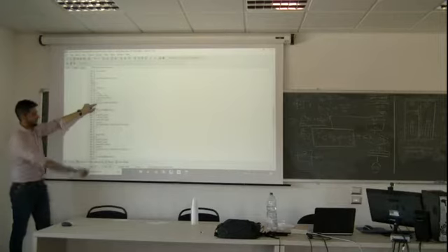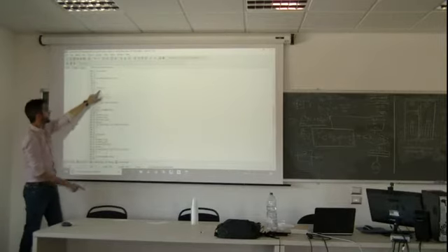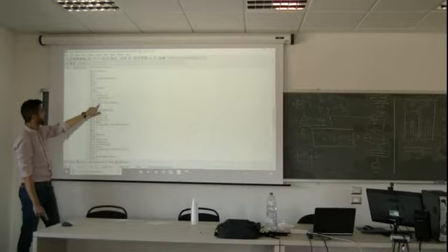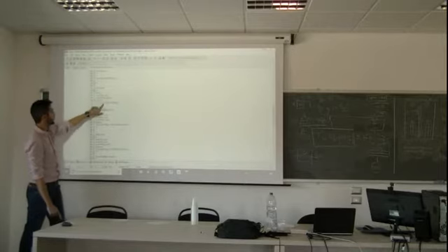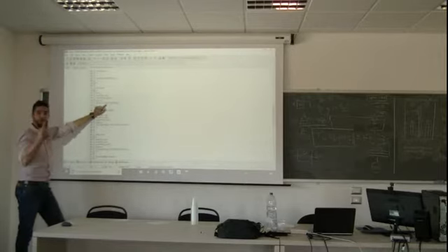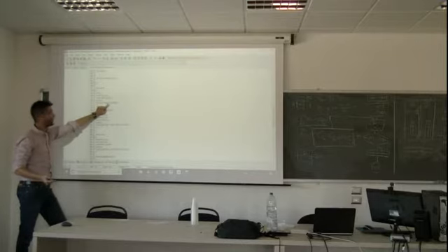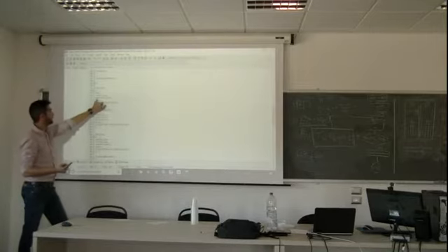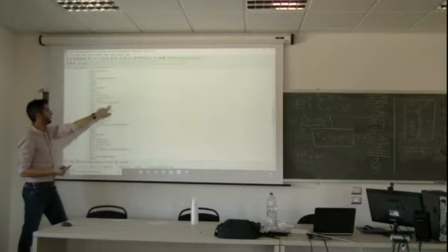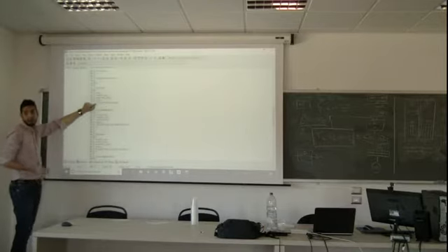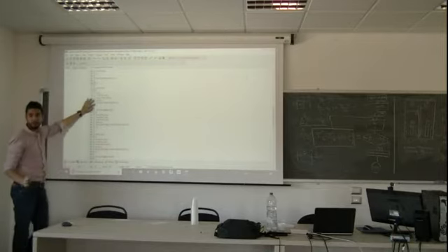In this way, I have the same equation, divided by A, divided by A, divided by A, for all the nodes. Now, the temperature of the node, when I is equal to 0, is equal to C, this coefficient, multiplied by the assumed temperature of node 1, my neighbor, TA, I plus 1. Because I is 0, this is the assumed temperature of node number 1. Plus D, everything divided by A. This is how I implemented the equation in the computer. Any question?